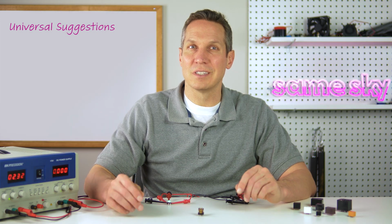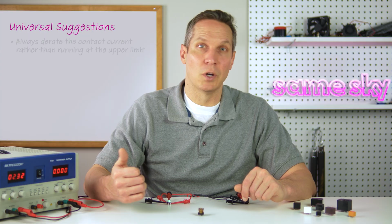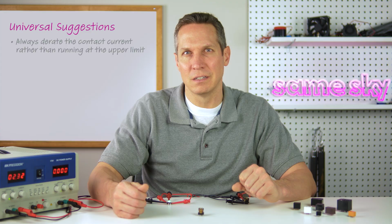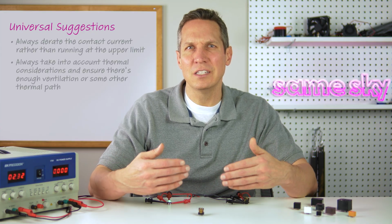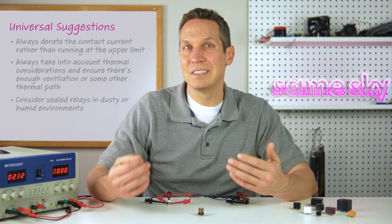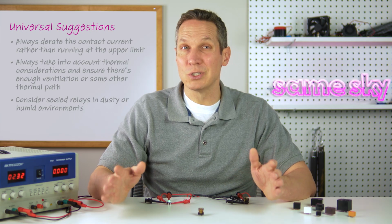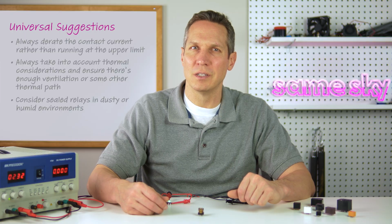Aside from those specifics, there are several universal suggestions that would help with any power relay. Always derate the contact current rather than running at the upper limit of the rating. Always take into account thermal considerations and ensure there's enough ventilation or some other thermal path. Finally, consider sealed relays in dusty or humid environments. All of these straightforward recommendations will go a long way toward improving long-term reliability.